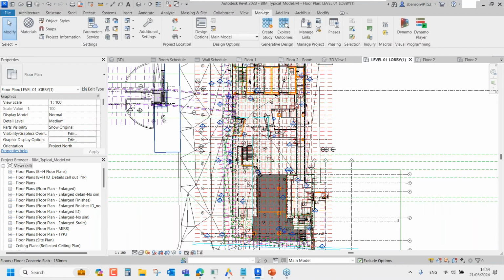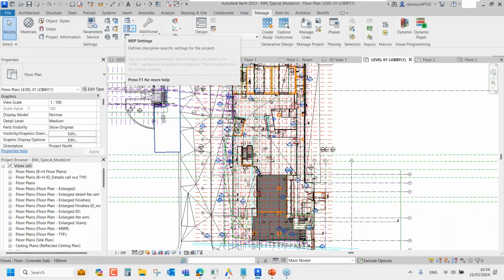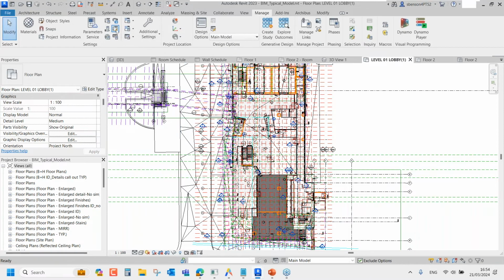Next, you want to go into this Manage ribbon. This Manage ribbon is really quite nice, because it allows you to do quite a bit of cleaning. For example, there's a function called Purge Unused Elements. This can be very useful because during construction and design, these guys add a lot of different functions to the model. So purging unused elements is a useful feature. I think I accidentally clicked on that. I hope it's not going to go and do that now. But anyway, it will help you purge out all of the stuff that's not really needed.